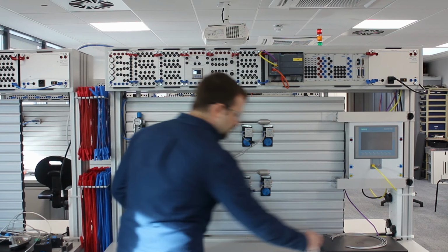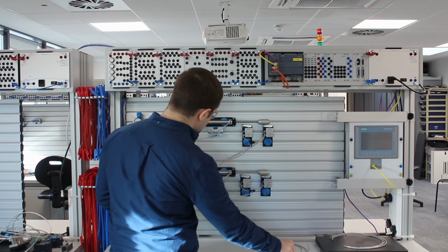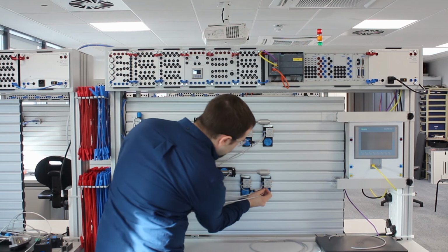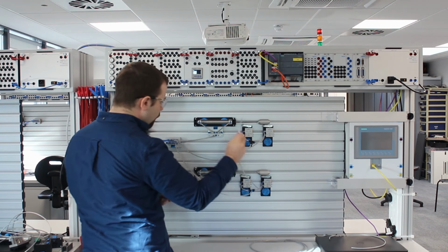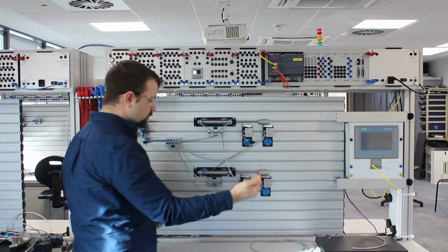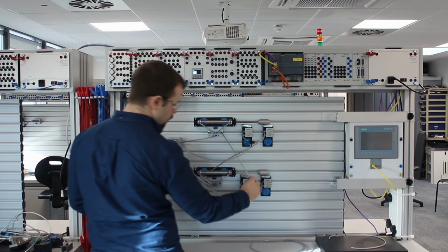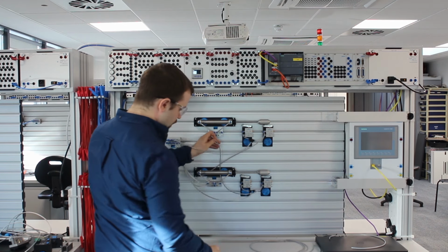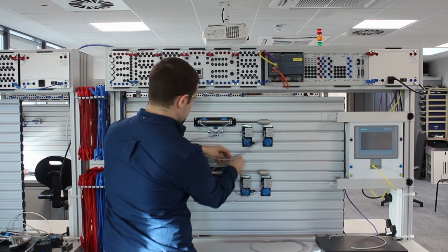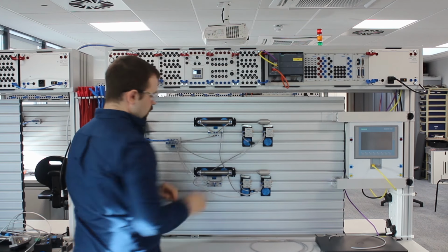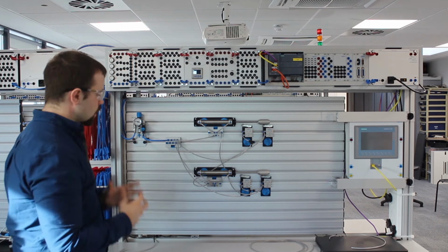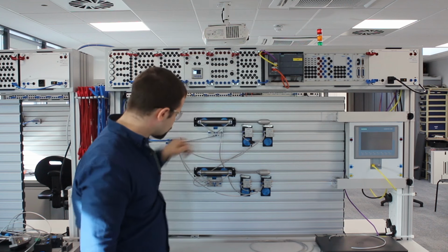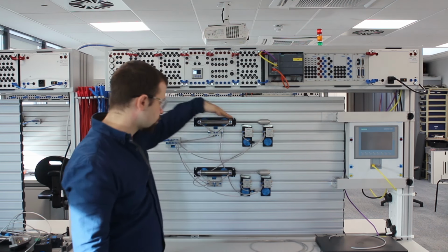Okay, so let's take another longish pipe, probably one of these ones. We're going to go from 2 up to 1/2, because remember we want it to retract 1/2. Again, it might be safer just to run this pipe behind this cylinder just to keep it out of the way. You can already see it's starting to become a little bit messy, but that's just one of the prices you have to pay. So, A will go forward, triggering this. B will go forward, triggering this.